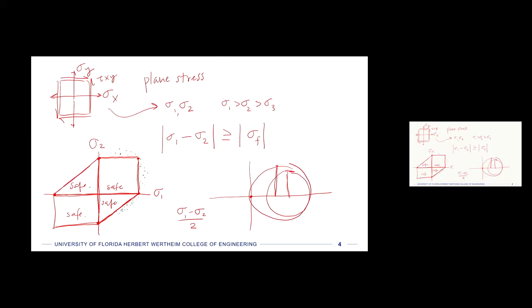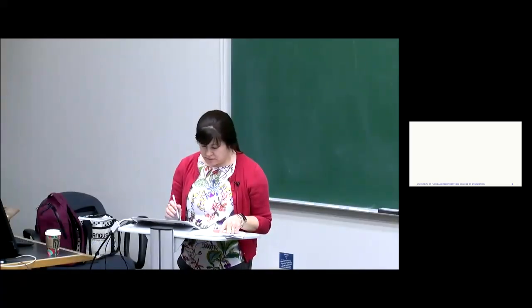Okay, so then we have to think our last thought about a triaxial stress state, where not only do we have sigma 1, sigma 2, and maybe sigma 3 that's 0, but now we have all of them, and they could all have positive and negative values. So how do we expand this failure envelope from a little biaxial stress state like this to a triaxial stress state, or a stress state in 3D? Well, we do that by expanding it along another axis. So we take our same axes that we had, and I'm going to draw them a little bit differently this time.